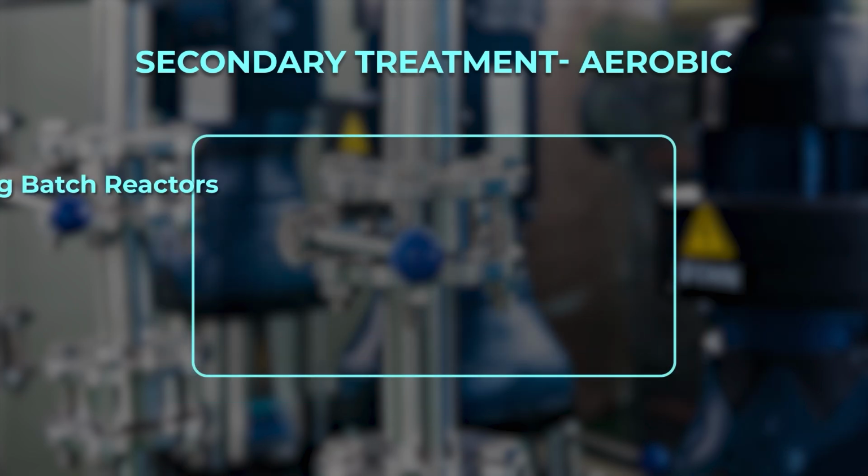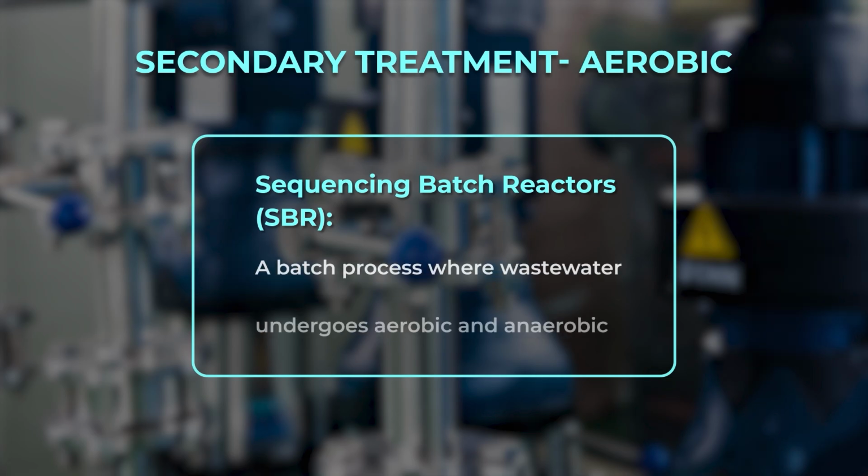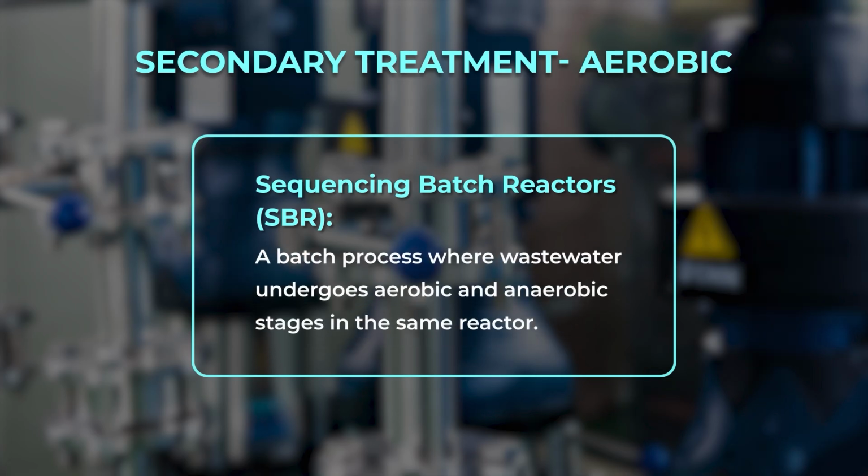Then another process is sequencing batch reactors, SBR. This is a batch process where the wastewater undergoes both aerobic and anaerobic stages in the same reactor.